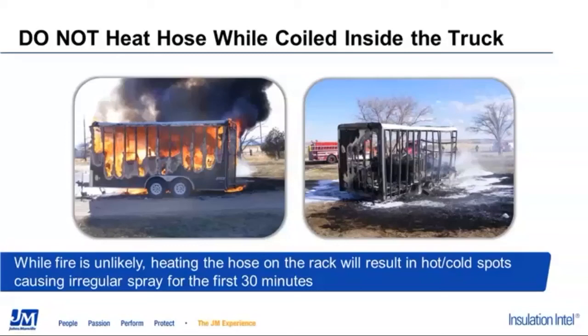This section of hose that's all stacked on top of itself is just getting hotter and hotter and hotter until ultimately it melts a hose or in the worst case causes a fire. Best case scenario is we actually end up with this issue where everywhere that the hose was stacked on top of itself, it accumulates more heat. Everywhere that the hose is loose, it accumulates less.